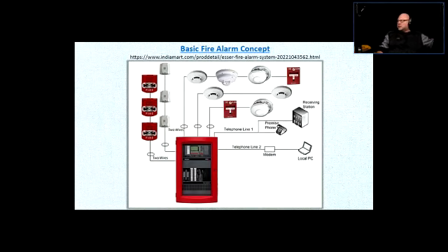Okay, now also what is involved in the fire alarm panel, it would be a communication section as well. So this fire alarm can be connected to a telephone line, to a regular POTS line, or it could be connected to a network in order to communicate with the monitoring station. Same as the security alarms, the fire alarms do not connect directly to the fire station per se. Right? So the fire alarm is not connected to a fire station. Security alarm is not connected to a police station.